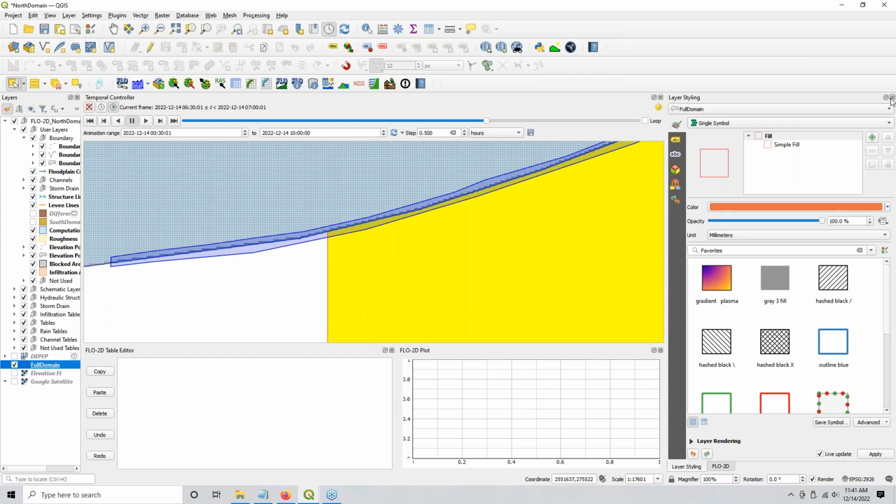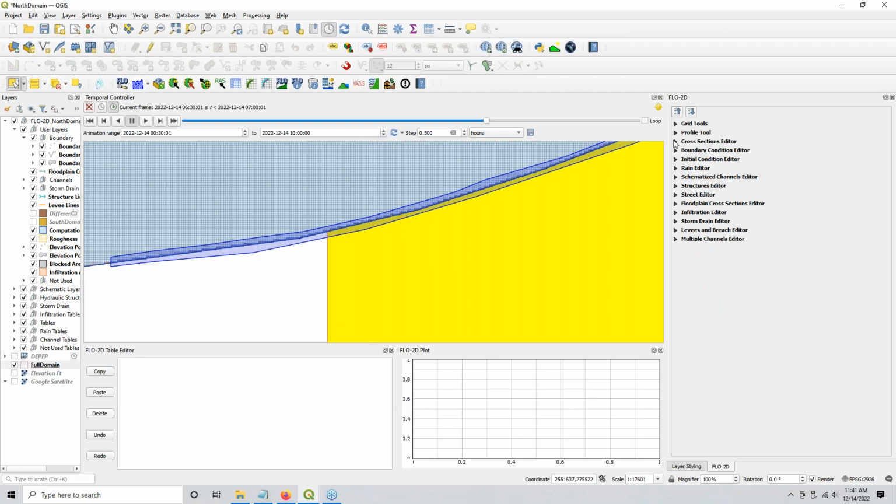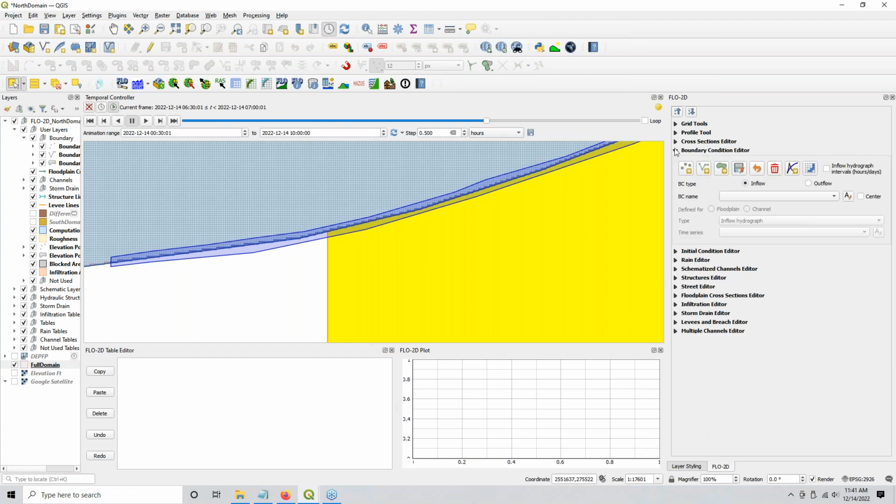Depending on the complexity of your boundary, you might want to use a split tool, but our boundary is not very complex, so we can probably just modify it or make a different one. If you wanted to split this boundary polygon because it was really complicated and you didn't want to redraw it, you could probably just split it into two using the edit and then using this splitting tool right here.